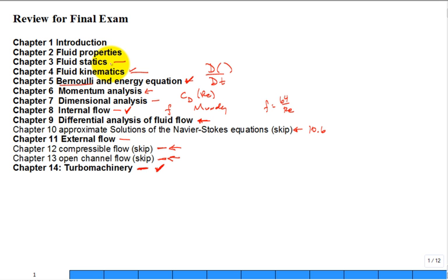because it's really surprising how often we have to go back to manometers and think about it, especially when we talk about the pressure in air systems. And I find a lot of people get confused. It's like, you're talking about inches of water column? Yep, in a manometer to measure that pressure.